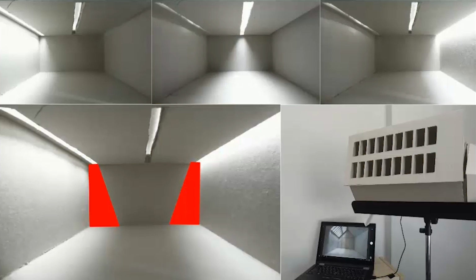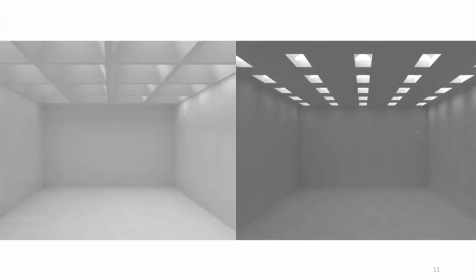And then the second principle was looking at the scale and the positioning of the skylights, and how moving the skylights around on the roof and the ceiling can create different effects in the light. One of the things we like to talk about is that you don't see daylight until it hits a surface. So when you're bringing in daylight from the roof, you can determine where you want that light to land in order to create the effect with the lighting that you're looking for.